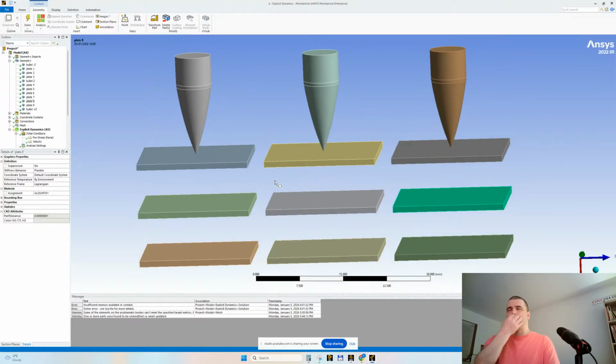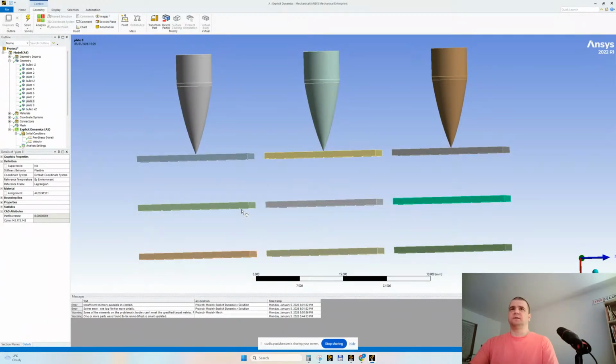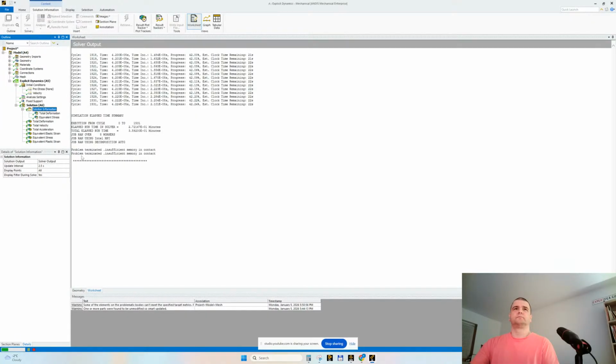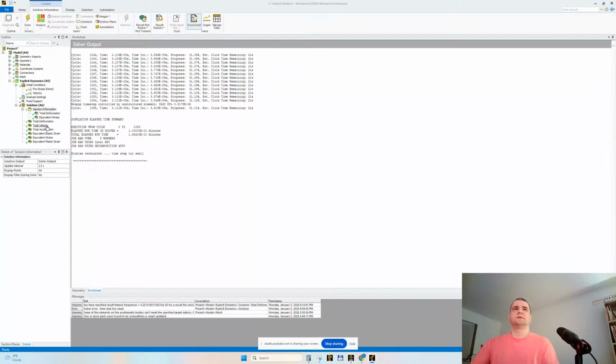Now we have, I promised thinner plates. Should I keep my word or not? Let me keep my word. Why not? Firstly, let's solve it quickly with these three aluminum alloys defined non-linearly. This is why it's nicer to work with the explicit dynamics. The solving is very fast.